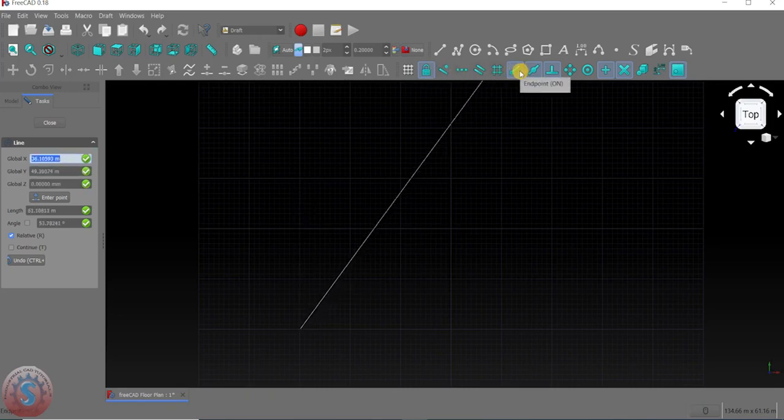You can observe on the top the endpoint. You want to highlight the endpoint, same as snap settings in AutoCAD. These are the settings you can observe. You want to highlight the nearest point, the extension, and the parallel lines. Like this, you want different types of them.